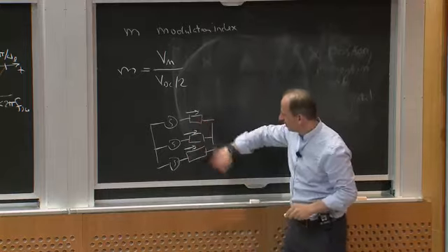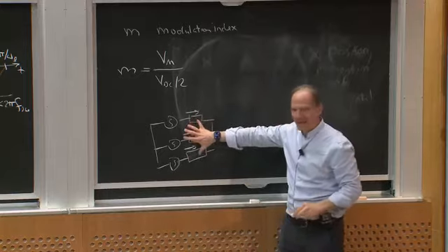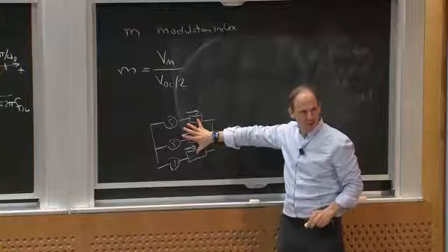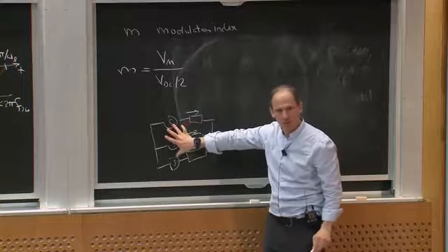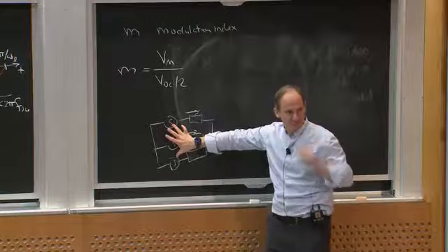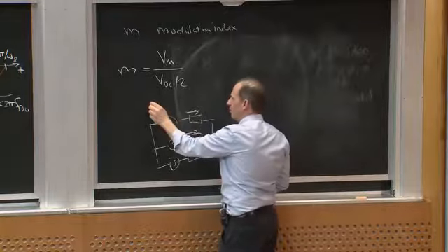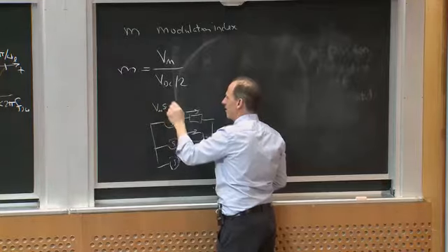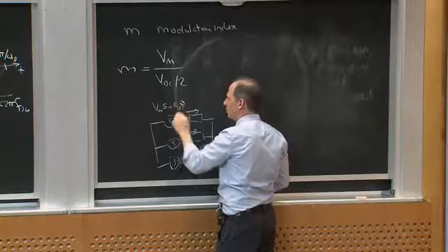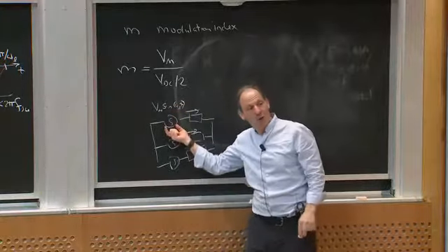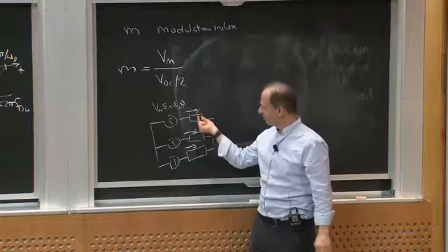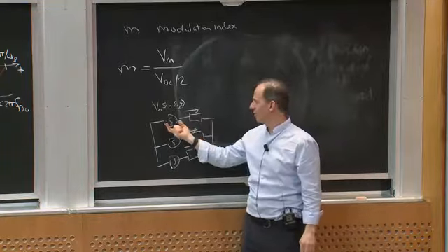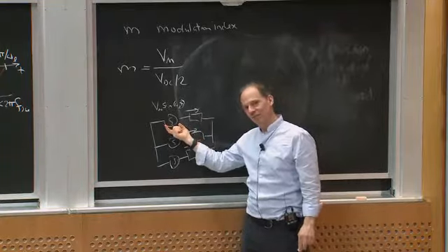At low speeds, the back EMF voltage of the motor is low, and I want low current. I want these voltage waveforms, which are now at the line frequency, V sub m sine of omega line t, to be small. But as speed goes up and the back EMF internal to the machine goes up, I want a bigger V sub m, for example.